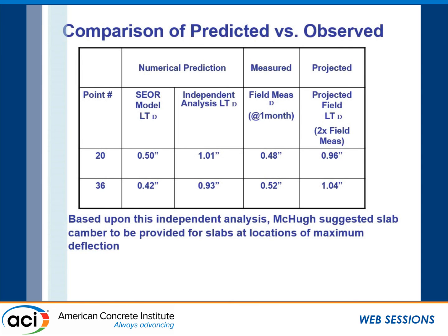As Eric had mentioned, specifying camber and actually finishing the concrete to maintain camber does take planning and really good communication with the finishers. They need to know where the camber line is, and obviously choose the appropriate finishing equipment to get it, because it can easily be erased.